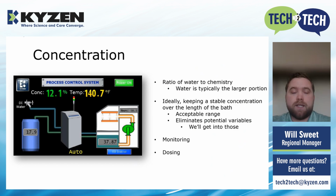So you're looking at an acceptable range. Say your part comes clean consistently at 5% concentration, so maybe set up an acceptable range of 4 to 6. Anytime that the concentration is between 4 and 6%, you know that you're in the acceptable range and you don't have to adjust the concentration at all. And when you do this, you're able to eliminate potential variables. If something does go wrong in the cleaning process, you can rule out the variable of concentration. You know that's not the issue. But we'll get into several of those as we keep going through this presentation.